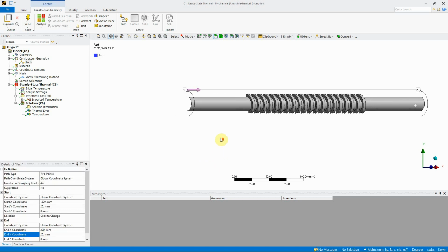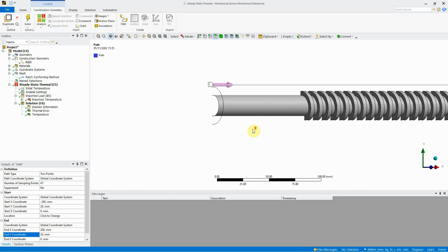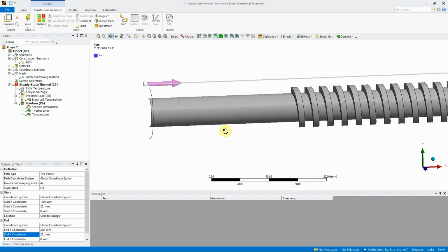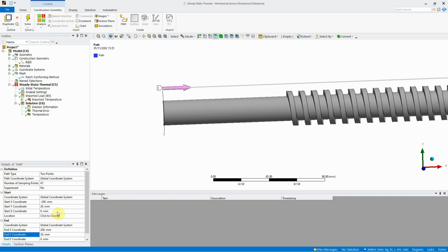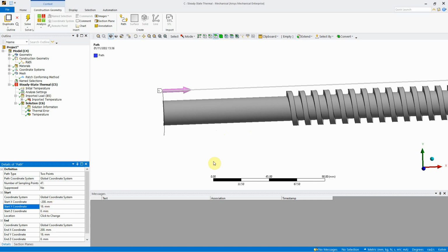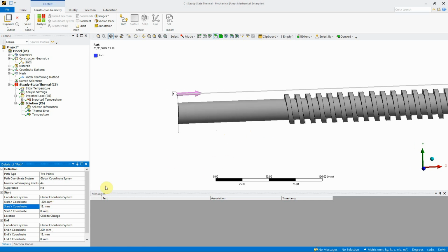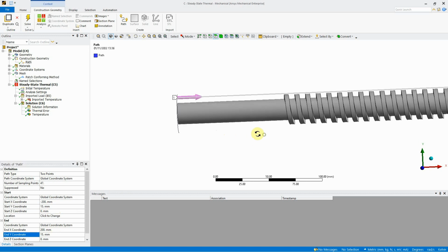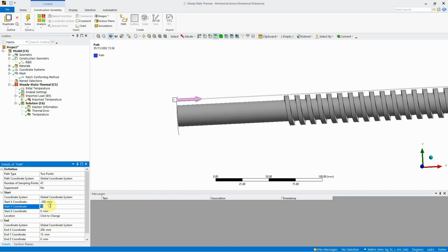So you can see that that will actually take measurements from the top of, oh, it's gone a bit more, not the top surface, 18, sorry. 18, and that's the actual top surface. So if I went a couple of millimeters below, so say 15, that's a couple of millimeters above, so say 16. You want to go halfway between the top surface and your spiral groove.